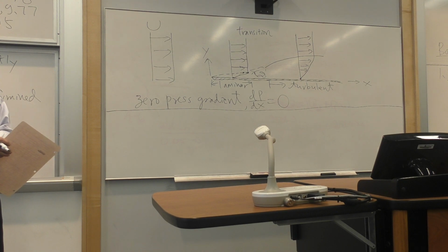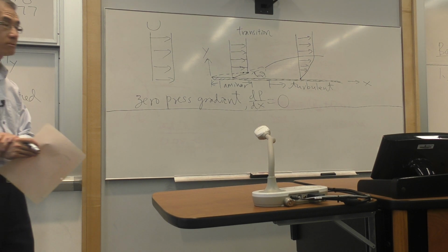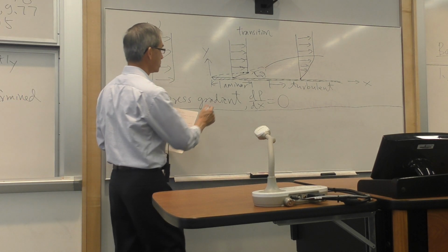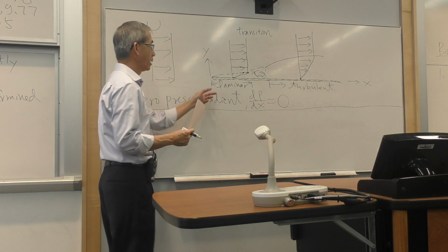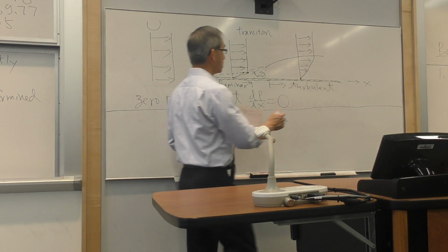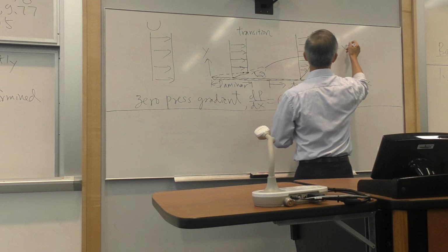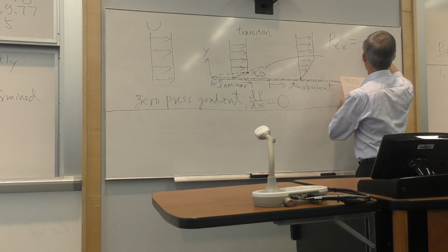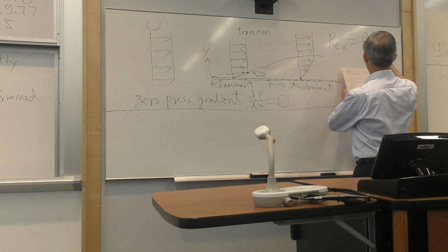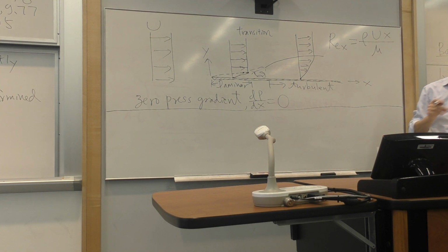Beyond that, the flow in the pipe becomes turbulent. Now I have a little different scenario, but a similar concept of laminar versus turbulent, in that when the Reynolds number, which in this geometry is defined by a length scale, not diameter anymore, but the distance from the leading edge, x, the rest of the Reynolds number definition remains the same: density, velocity, viscosity.